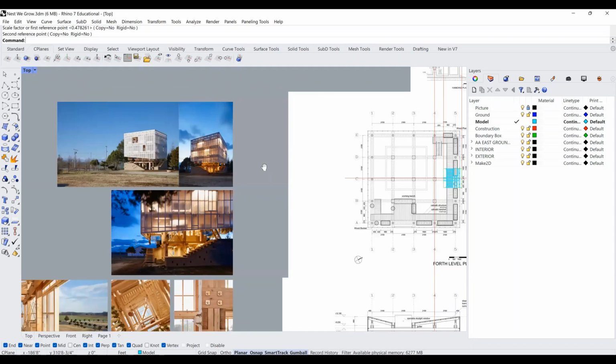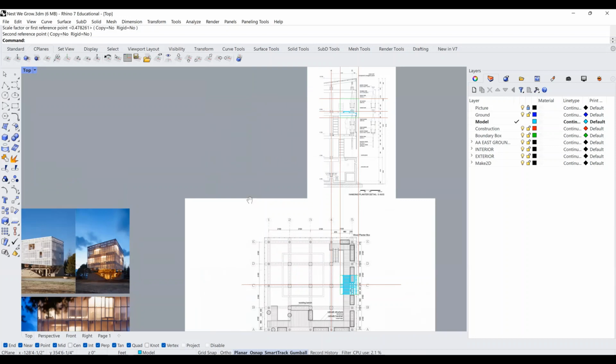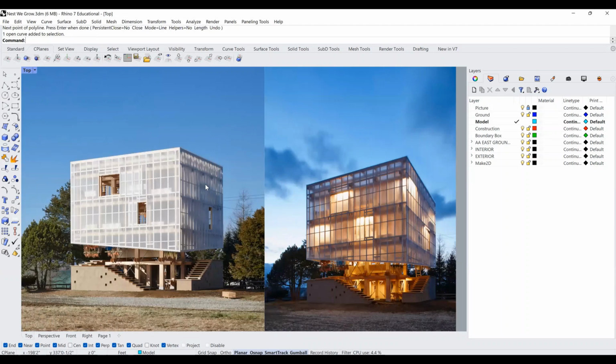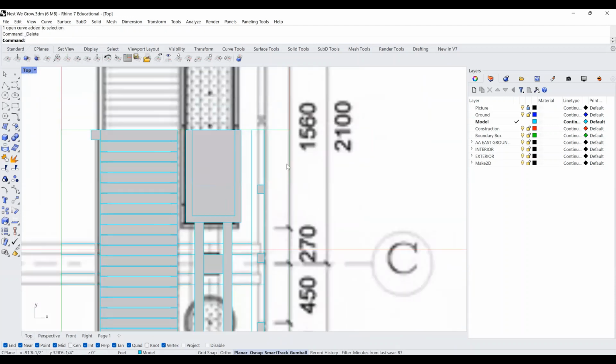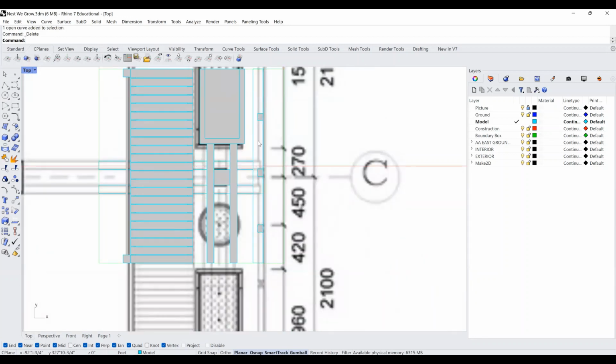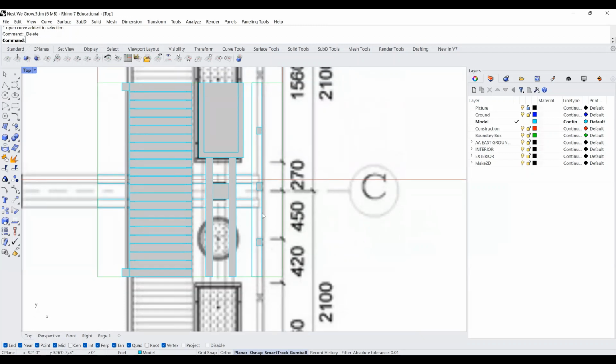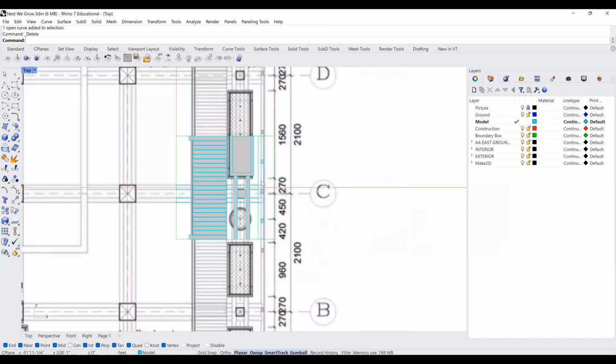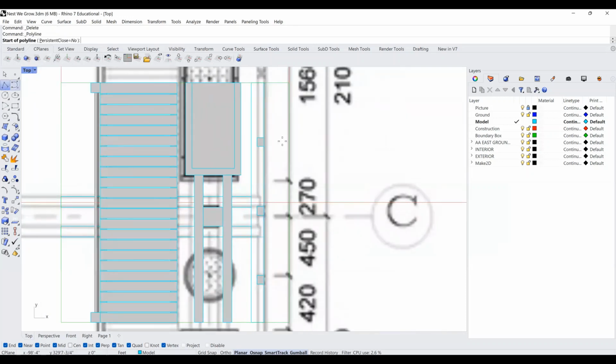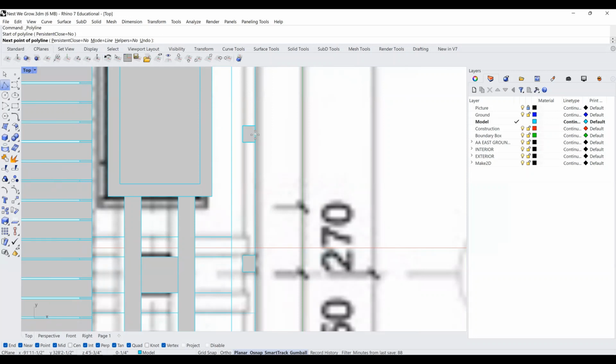We should model that. And so what I'm gonna do is that, actually at first, we have to know that the corrugation itself is something like this. It's this sawtooth kind of shape on a corrugated panel like this, and we're gonna model that in Rhino too. So I'm gonna start by putting onto these main cladding framing, which is regularly spaced out between these frame posts, if you will. And so I'm just going to build it on this face first. And for the purposes of this tutorial, I'm just going to assume that this is going to be maybe an 1/8 inch corrugation.